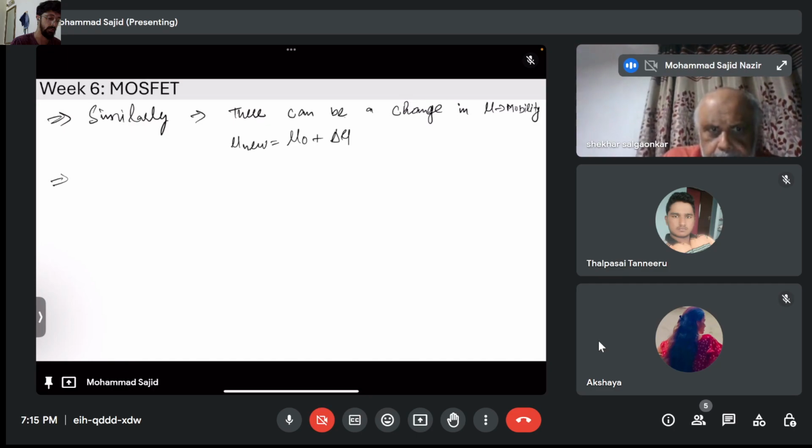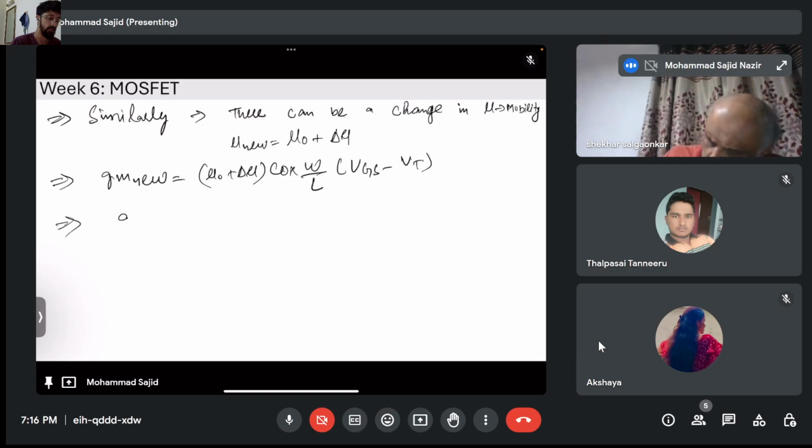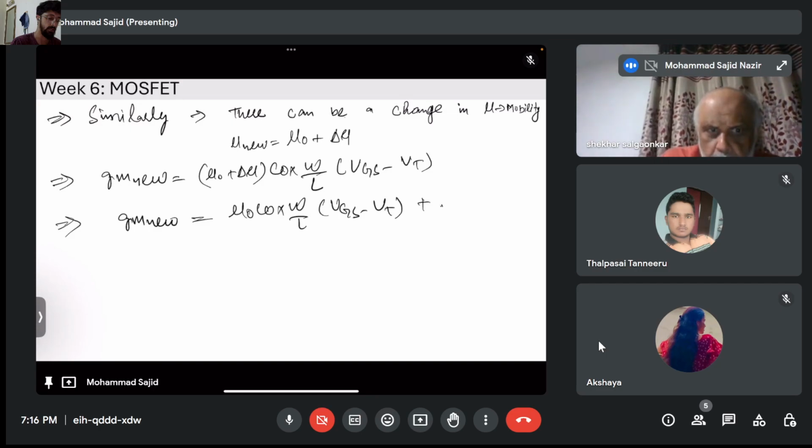So what if it is happening in the circuit? My GM new will be mu naught plus delta mu, C ox W by L. Let's say at this time VT is constant, so I will just treat it as VT. We will see only change with respect to mu naught. So GM new will be mu naught C ox W by L VGS minus VT plus delta mu C ox W by L VGS minus VT.